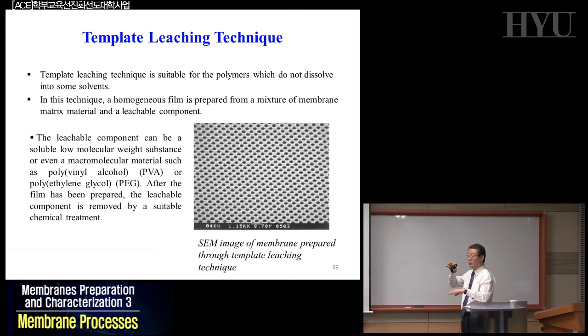You see the very nice picture, just like lithographic ones, and you can make the template etching. What you do is expose UV light or X-ray lithography through these templates, and then you have exposed regions and unexposed regions. I can show you my own picture, which appeared last year in Small, where we used polyimide, and polyimide is very sensitive to UV exposure or X-ray lithography, so you can make a very similar picture like this, and it could be used in fabricating electronic devices.